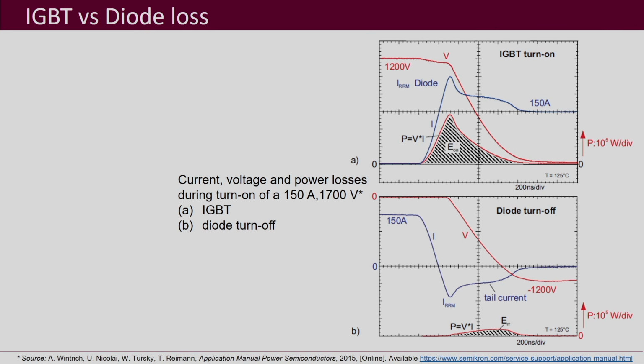Now, one thing that I wanted to mention here is that you have got an IGBT plus an antiparallel diode. So, you will need to do the loss calculations when you want to calculate the efficiency or do the thermal design of your converter.